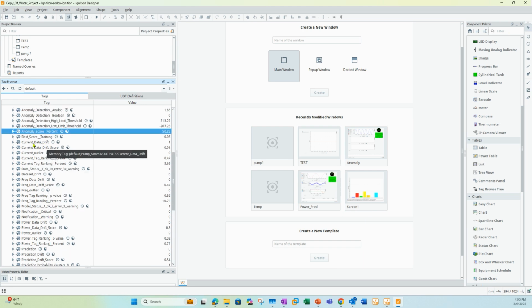So every single input, we analyze data drift, we analyze the drift score. We also analyze the outlier detection. If the current is outside of the statistical outlier, it will also provide an indication that it is either deviating or it may have a drift that's associated with a calibration problem or some indication that it's not within the statistical limits.